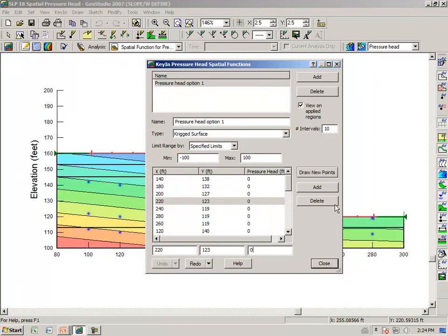But it is also possible to draw the points, and for example, if you had a contour map and some ideas of the contours, you could just provide a series of data points along each contour. Once again, it's possible to do a linear interpolation or a Kriging surface or none. In this case, we have used a Kriging surface.